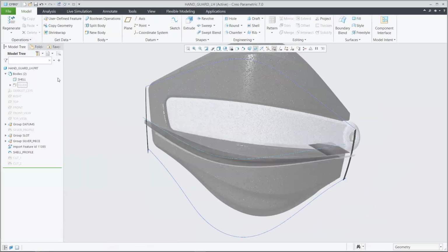Now, we can use different capabilities inside of Creo to make our lives easier, starting with multi-body capabilities. Those can be used as part of our surfacing design, and as we're building out the shapes, we can use the multi-body to maybe bring in geometry from outside resources, like an assembly that might be interacting with this file, and using it to cut elements maybe of our handguard, which we'll do at the end of the demo to piece those components together and fully build out our assembly. But let's actually start out by building out the cover itself.